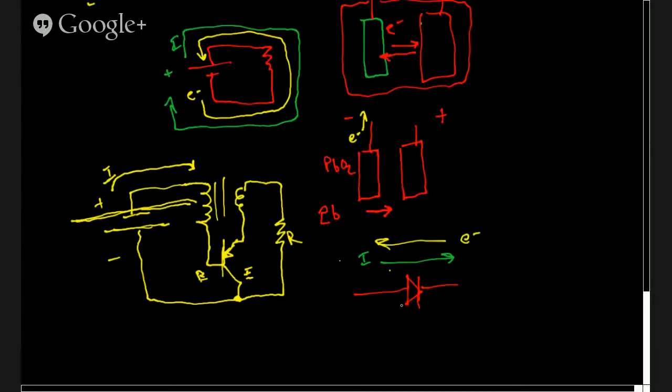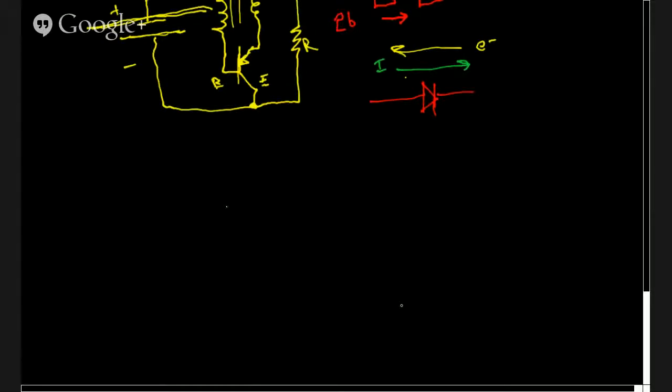Nowadays there's a movement to high efficiency, high voltage DC distribution. It used to be the case 100 years ago that changing voltages from one to another was hard in DC. We didn't understand switch mode regulation and buck boost converters, which we'll cover next class. And transformers are an easy way to do that with AC.